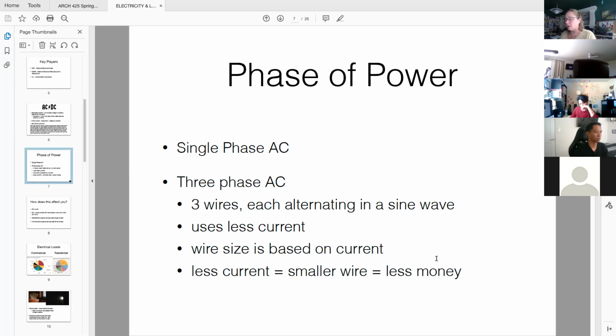A lot of architects end up doing a lot of high-end residential, where you're talking about a 20,000 square foot house, which starts getting into the commercial scale of buildings with much larger heating and cooling loads, but you're stuck with residential sized equipment, and many residential areas don't have access to 3-phase power. So I just bring this up because it could potentially be on a project that you've come across somewhere down the road.